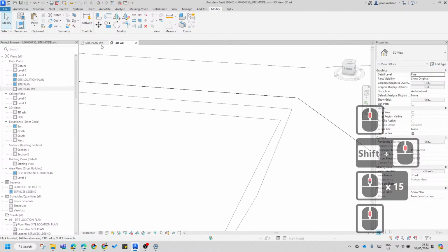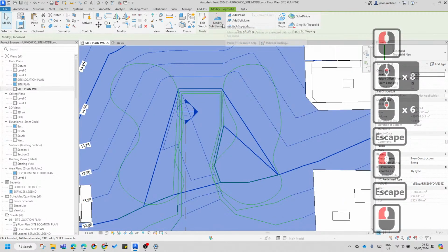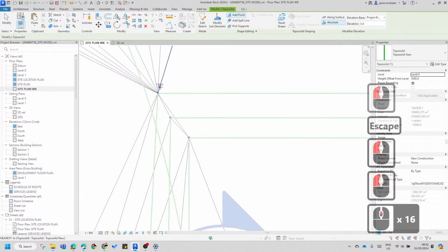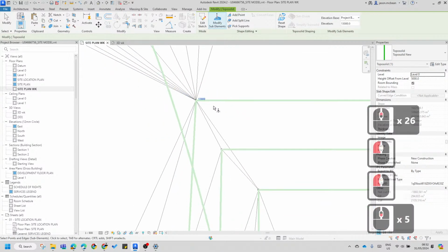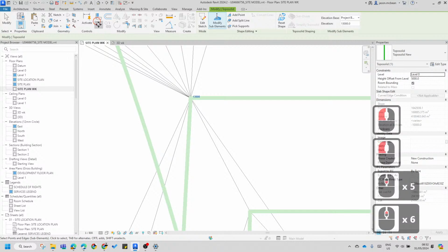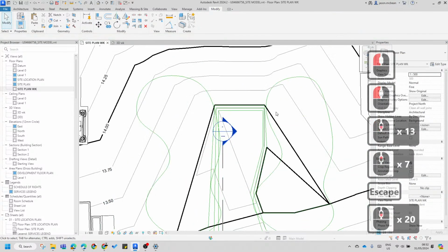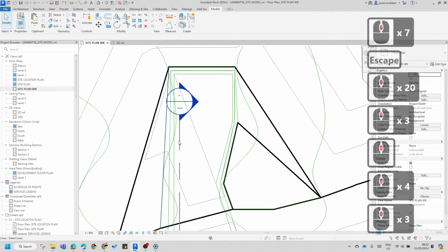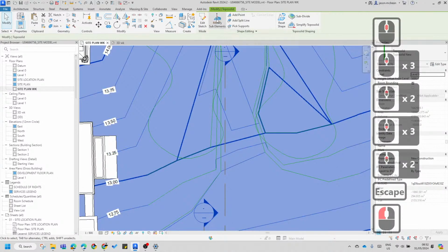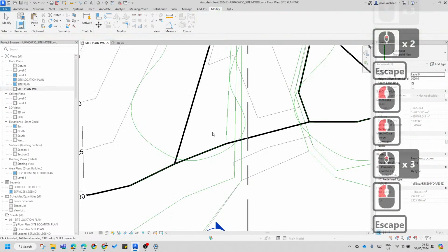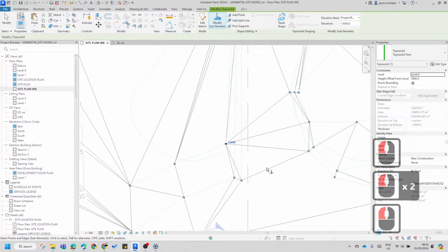But now, what's cool is, when you want to start refining the slope, select this and go to edit point. Now you can start moving these closer. Modify, so now you can move this point. See this move command? You can now refine what you're trying to do here. Here you can see it's created a bit of a flat spot, but this is modify points, and let's check what that point is, 1300. So modify that, 1300.